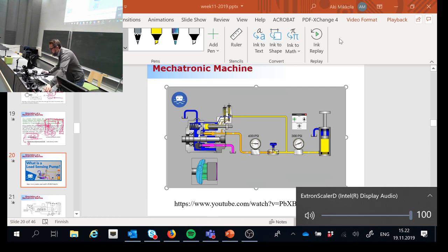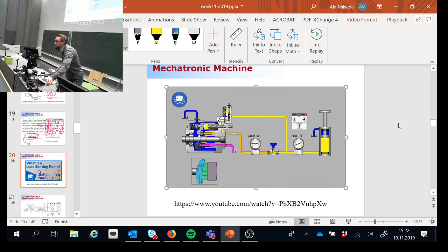Pumps, sometimes referred to as flow compensating. Our pump still has that very heavy spring, that major adjustment called the pressure compensator or the pressure cutoff for when we hit that really high top end pressure to make sure our system is protected. But it also has a weaker spring called the load sensing adjustment or the flow compensator.